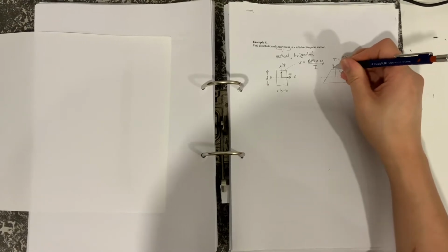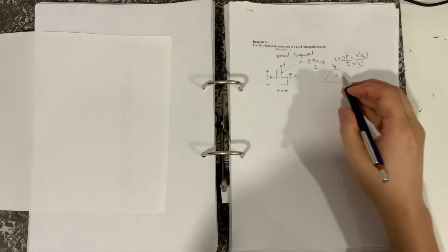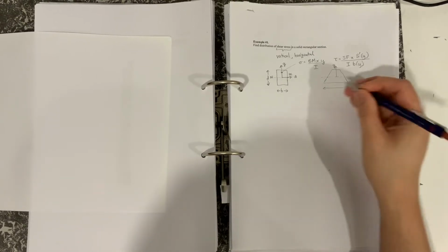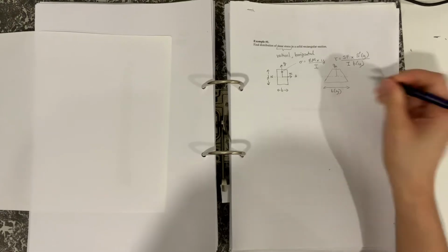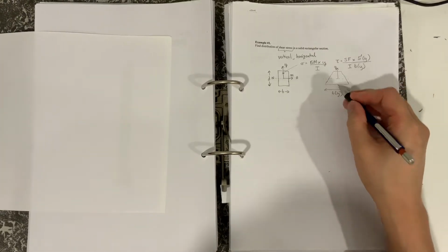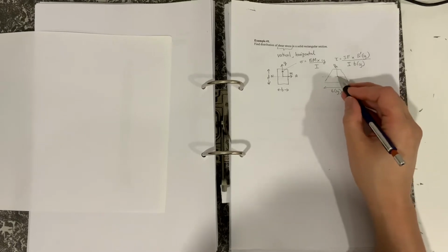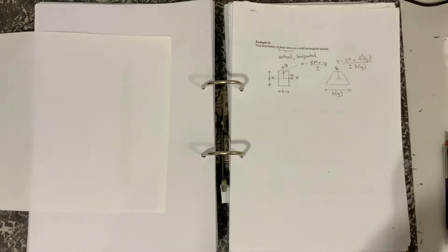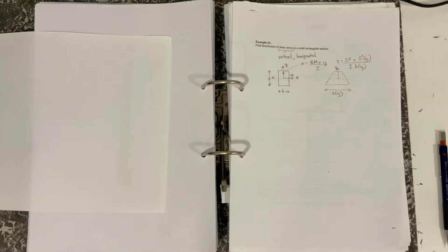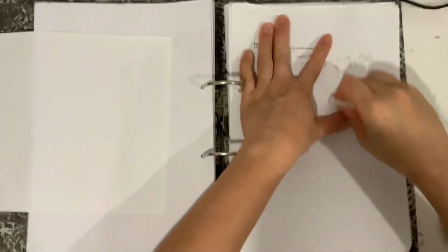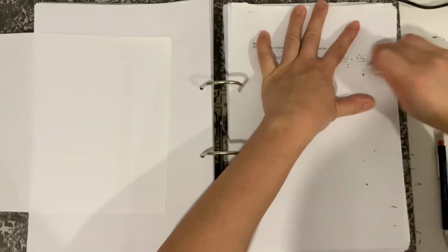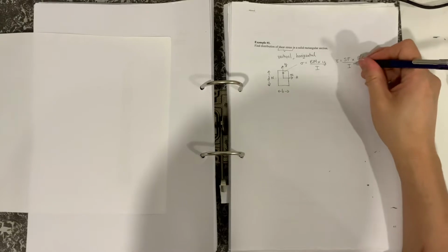So if the cross-section had looked something like that, then we can see that b, the breadth, is a function of y. So when y is here, it takes that value there, and when y is 0, it takes that value, and when y is at the top, it would take that value. But for a rectangular section, it's obviously constant, so it's not a function of y. So for the case of a rectangular section, I'll just call it IB.